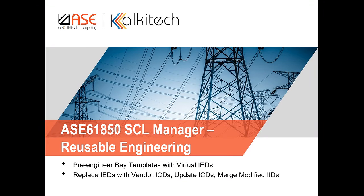Hello and welcome. This session is about IEC 61850 SCL Manager, that is the ASE System Configuration Tool. We'll be focusing in this session on reusable engineering. In reusable engineering, we will talk about pre-engineered bay templates with virtual IEDs. This is a concept that you can leverage to add more fine-grained detail to your system specification descriptions, or SSDs. We'll also talk about the replace IED use case with multiple specific use cases.